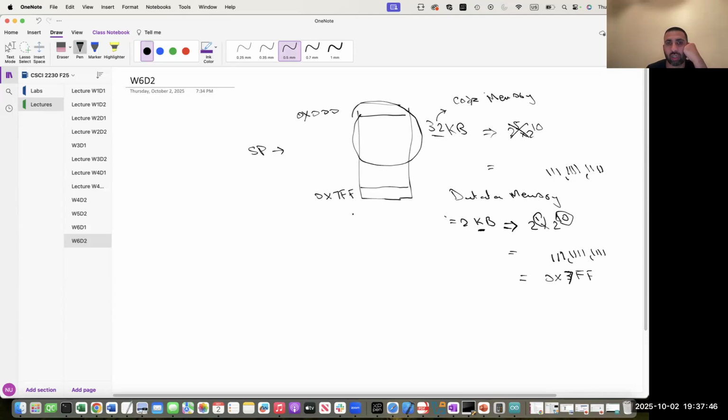as a user programmer. So we need to make sure, for example, if we are setting a stack pointer such a way that it points to a location in the memory, it should not point to a location which has already been used, right? Even if I'm setting stack pointer equal to 0x7ff and it is pointing to this location, I need to make sure that my program is not using the same location for holding multiple data, because then I will be overwriting my own data and I will lose my data. So the program will not work in a way I want it to work.